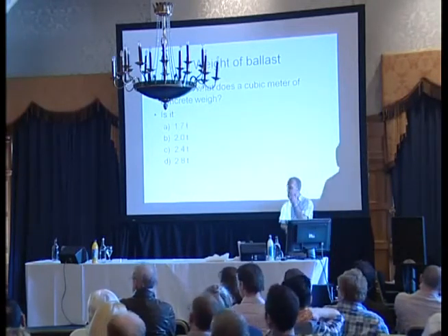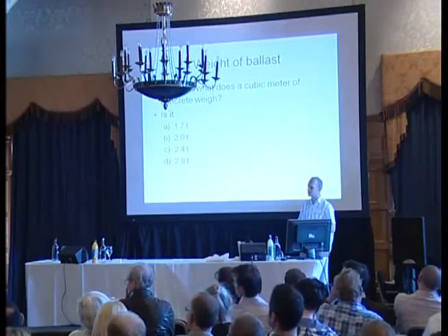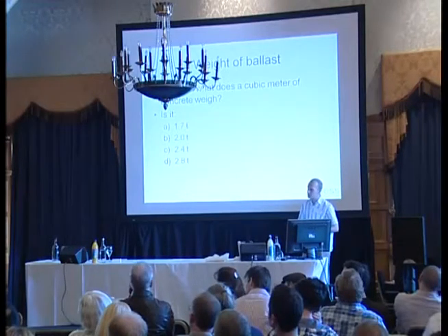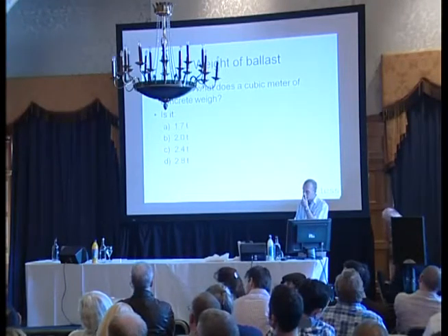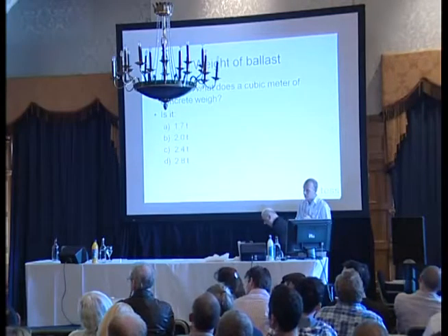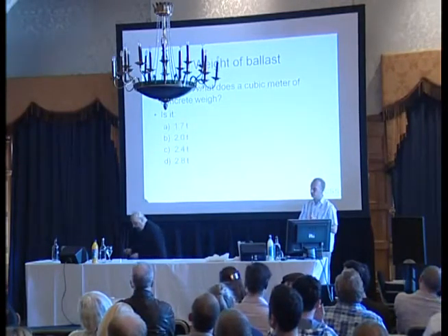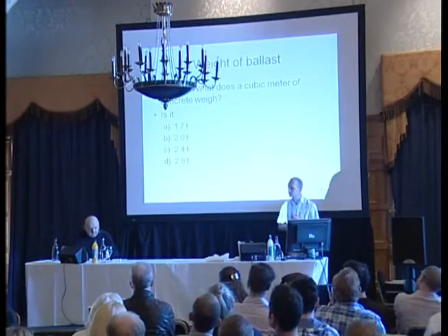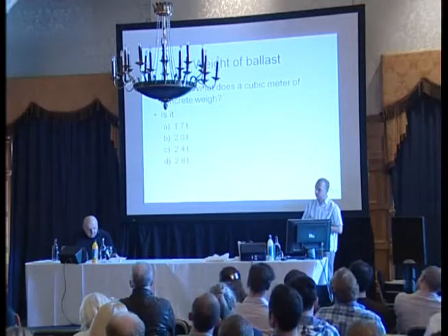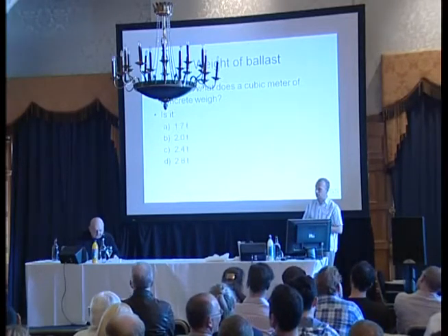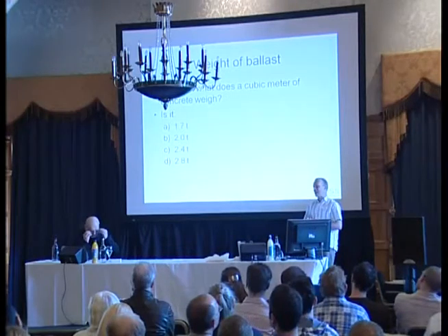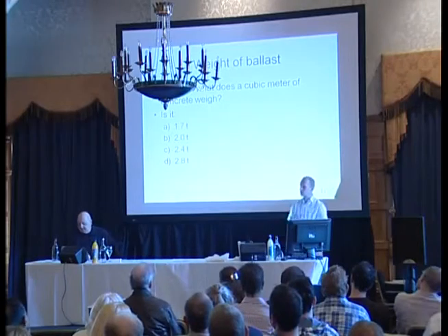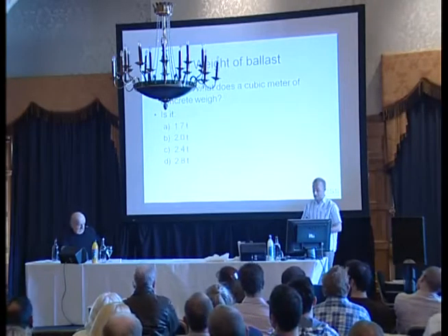Would you take that as a good average for a cubic metre of concrete? Yeah. If it's a big chunk of concrete on its own, it depends again where it's made, because of the aggregate weights. So it can vary between 2.3 and 2.5. 2.5 if it's full of steel. There's lots of steel reinforcing in it to make it stay together as one. 2.3 is just a lump of concrete. So if we allowed 2 tonnes as a safety officer, and you saw a cubic metre of concrete, and you said that's good for 2 tonnes, you'd be pretty safe, wouldn't you? Yeah. Okay.